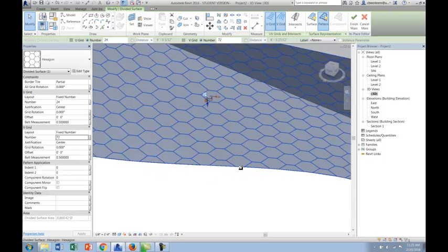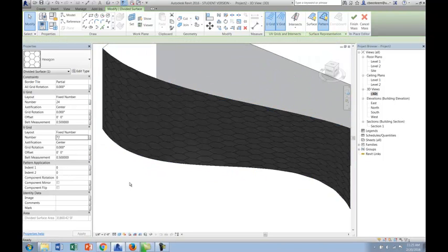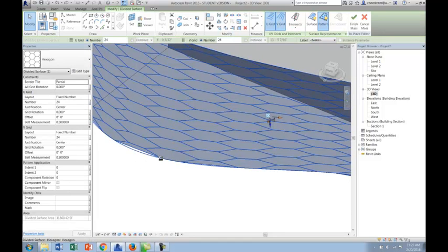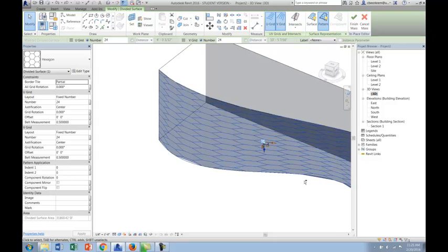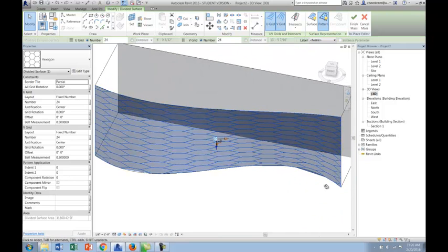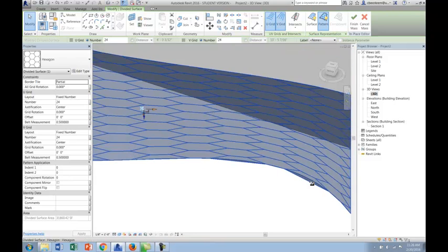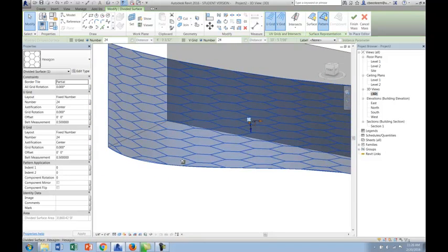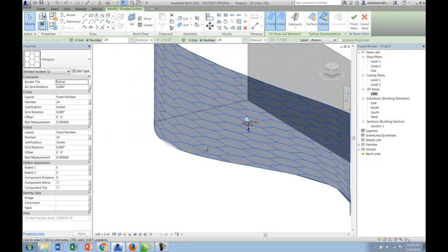Again, down here, if I go back a little bit, when the panels have a longer edge, they're going to break free from the actual conceptual mass. It's making straight components along here, whereas it has to in order to keep each of these different faces planar. What it's trying to do is just keep each face planar in the system. So there's a variety of different pieces you can use here.